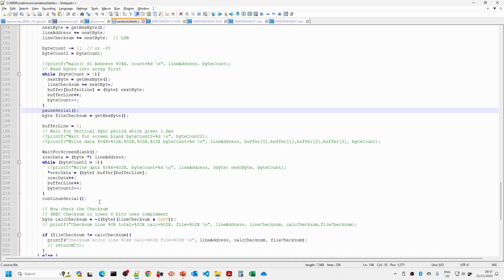And if we didn't do this, what was happening is we were missing a couple of bytes, and then the S-record checksum would fail and it would abandon that particular row. So when data was coming out on the screen, you'd end up with chunks missing, so sort of gaps in the video display where it wasn't getting the data.